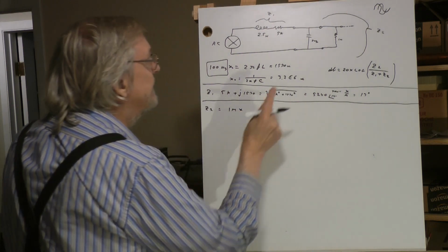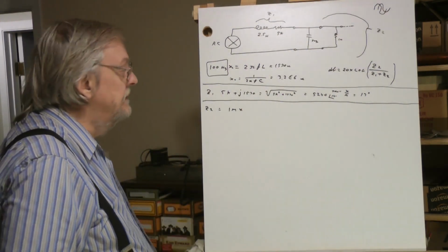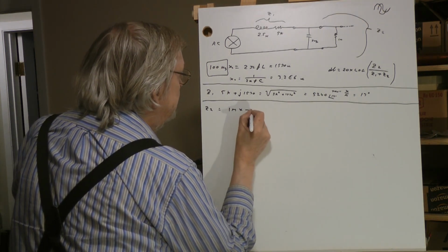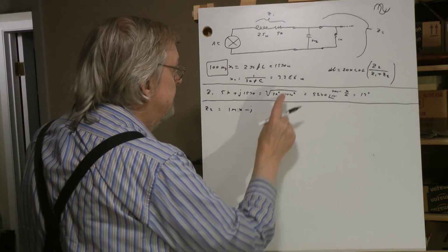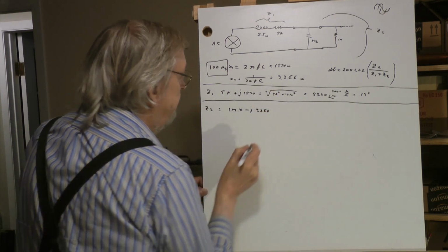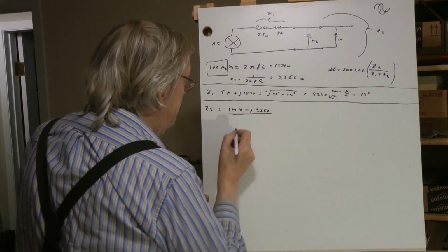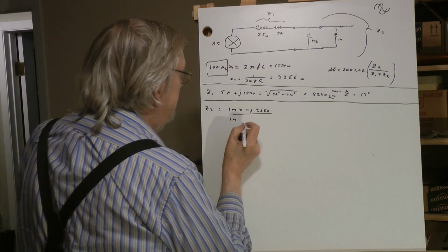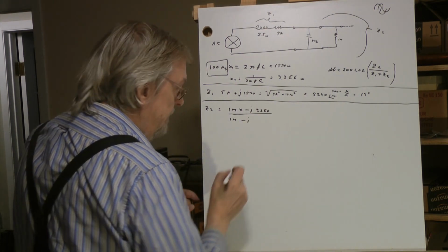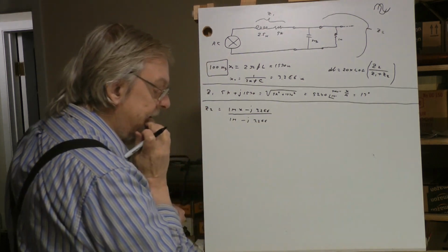times. Now again, that's out of phase, it's a capacitor. The phase is reversed, it's minus 90 degrees. And we indicate that by saying it's minus J, and it's 3.2 E6, right? 3.2 E6. And that's going to be over the addition of them, which is 1 meg, plus minus J, which of course simply becomes minus J, 3.2 E6.